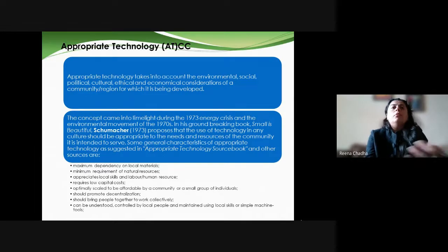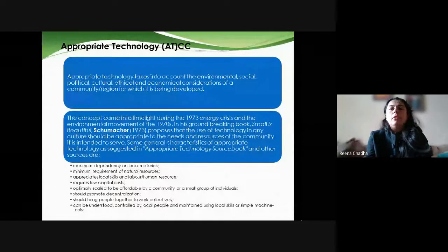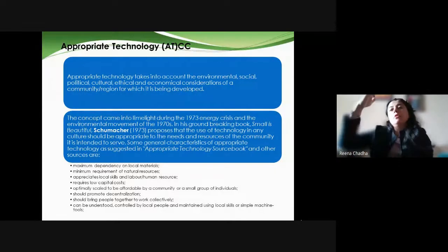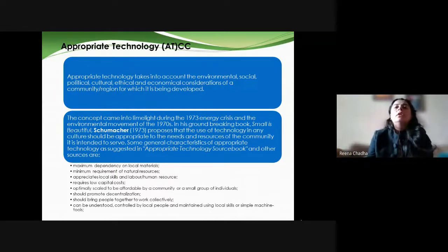They have to be told about the global problems, about the risk in future of degrading water quality, about the kind of TDS parameters, about the water quality parameters, BOD, COD, which can be there in their water, and how rainwater can help in dilution of those pollutants, in recharging of the groundwater, in increasing the level of groundwater. Even when groundwater goes down by 1 meter, 1 unit power consumption increases, because you have to pump from more depth. So if people understand these concepts, they will think, "Okay, my electricity use will be higher to extract water, so I will ensure that the water level doesn't drop."